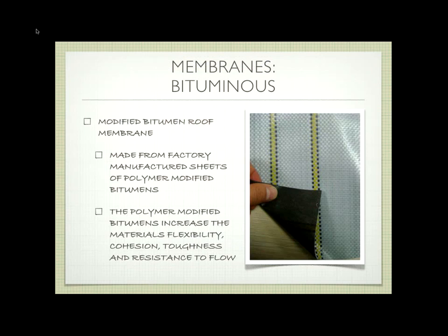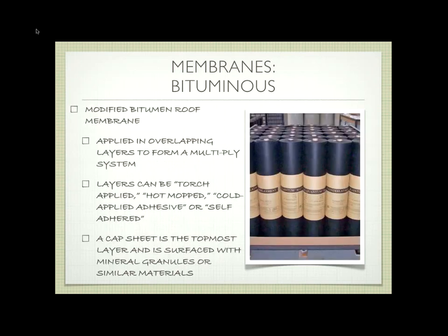So now we can also have this bituminous roof membrane. This is the one that I can't find an example of. This is a specially engineered material. It can be self-stick, sometimes it can be flame stick, where you've got these various pieces, so instead of using the felt, it's actually more of a rubberized piece that sticks to itself. And so you can use that. I'll have to dig around and see if I can find one. I know there's an example here somewhere. So it's been engineered for this purpose, which is the important thing to understand. So it's better than those layers of felt that are overlapping.